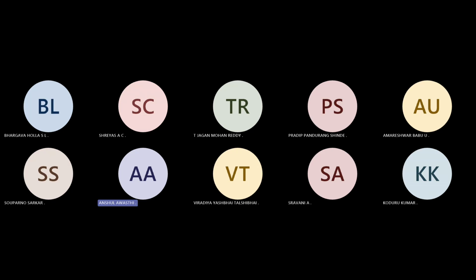Every time we need a variation graph, we need to change the value and run the simulation. So this is not practical for large practical applications. Let us say we want the ID/VGS relations for 100 values of VDS or 1000 values of VDS. For that, this simple technique is not feasible. For that, we have to go for the advancement of the tool. So in this lab particularly, we will see how we can parameterize the value. For example, we need the variations for 1000 values. How we can do that and how to use it in the tool, we'll understand in this class.